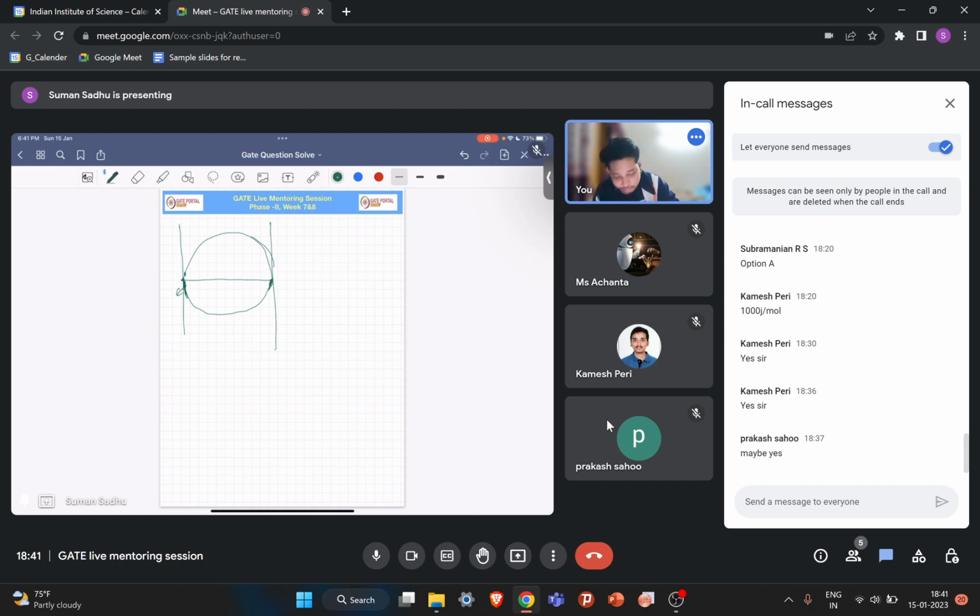So near your pure composition or pure elements, your slope is minus infinity. That's why here your free energy will always decrease initially. Then when this delta H part dominates the minus T delta S part, it will increase, and similarly on this end also it will decrease. So because of the nature of your delta S curve, your free energy curve will never look like this, because it can never go in the positive direction here. Always it will start from the negative direction, and then it will go up.